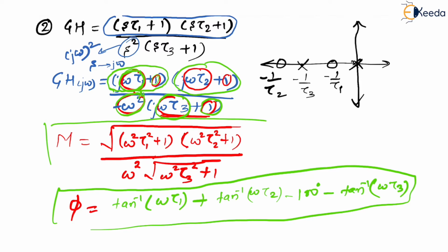Whereas on top of that I have also found out the magnitude. Now step 1. Step 1 is to find the magnitude at omega equal to 0 and magnitude at omega equal to infinity, which is nothing but m0 and m infinity. So yes, let us start with that. Step 1 is to find m0 and m infinity.